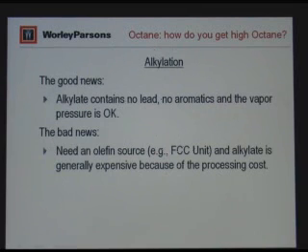Now, the good news: alkylation has no lead, has no aromatics, vapor pressure is okay, and the octane is reasonably good. It's not quite as high as aromatics, but it's pretty good. The bad news, unfortunately, you need a source of these olefins, so typically another cracking unit like an FCC will make lots of olefins, and the alkylate's more expensive because of the processing cost. You know, nothing is free. If you process, obviously, there's utility costs, capital costs. So alkylate's a prime blending component, but it costs money. All right.